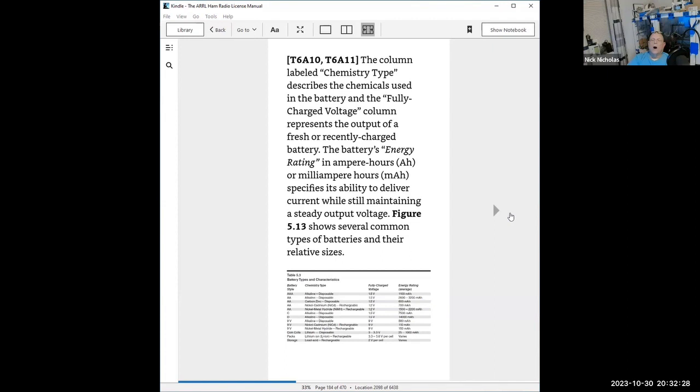If you exceed that value, there's a short window you can get away with it, but it's risky. If you do, more times than not, you cannot get that lithium battery to charge again, because the battery management system doesn't have enough power to engage itself. If you go beyond that point, you will start a fire or an explosion. Don't mess with playing with the range of lithium batteries.